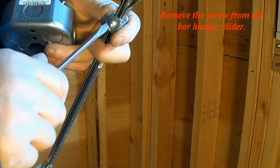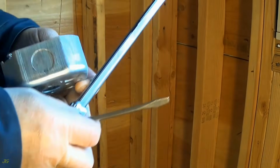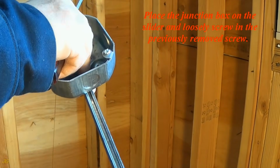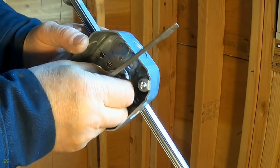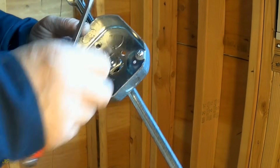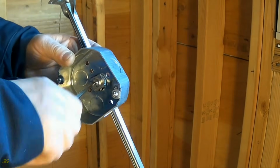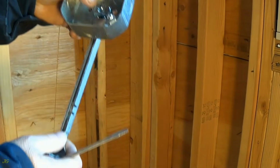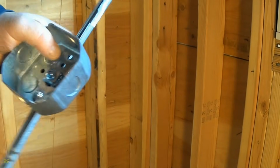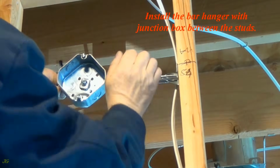Remove the screw from the bar hanger slider. Place the junction box on the slider and loosely screw in the previously removed screw. Install the bar hanger with junction box between the studs.